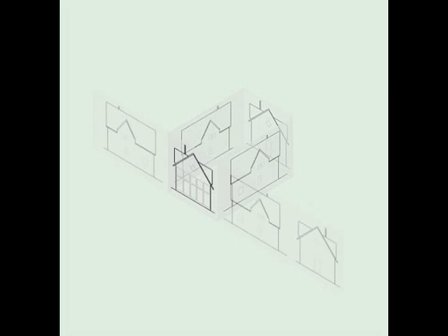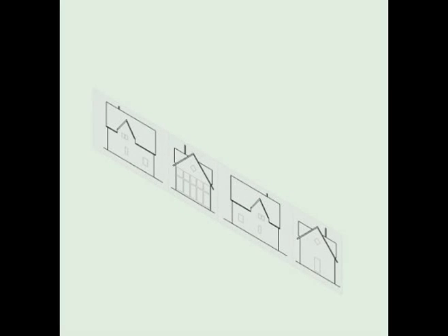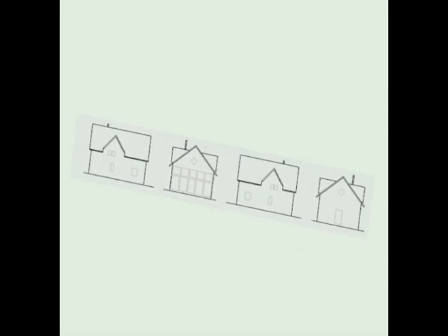As we move around a building, we see a series of related elevations which change as our viewpoint changes. We relate these views to each other by unfolding the vertical picture planes on which they are projected, forming a horizontal sequence of drawings.